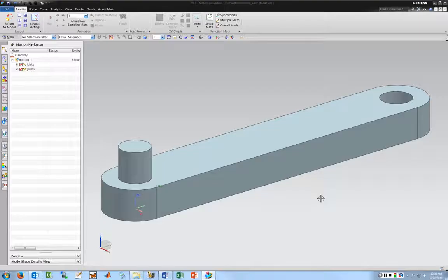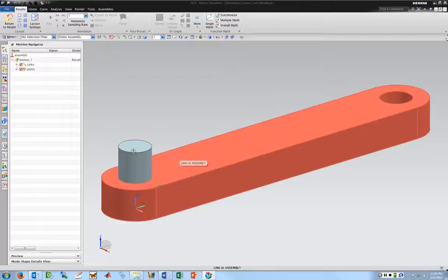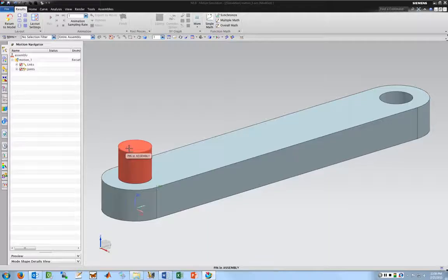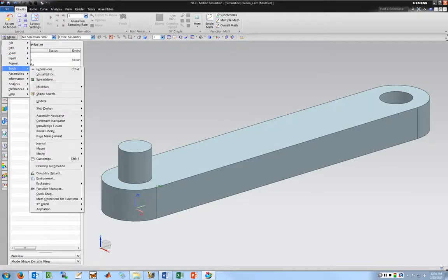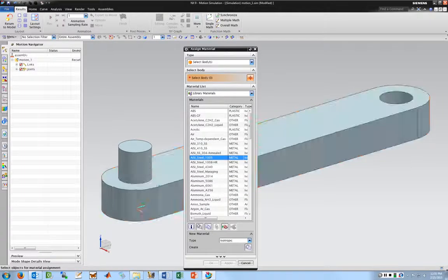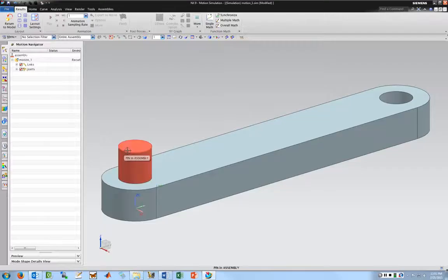Okay, I'm back. I'm guessing what's going on is that since I'm assigning these in motion simulation, and this part is fixed, it just doesn't accelerate, so the mass properties don't mean anything. And I'm assuming since it treats it as ground, it won't let you set the material properties for it. I've tried a couple different things, and that's what I'm guessing is going on. The part that actually does move around, you can definitely set the materials for, so that's working just fine. It's just the ground part. I think that's it.